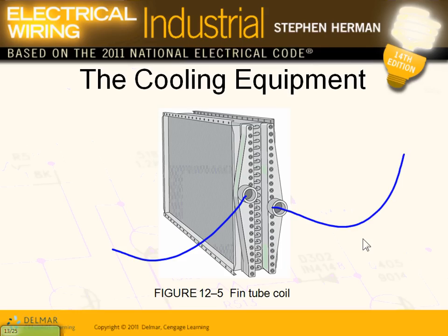This coil could be in the air handling unit, that would be an evaporator. Could be in the condenser, or it could be anywhere else. As a matter of fact, it's just bringing some type of hot or cold refrigerant into it, and you're blowing air right through it through a fan. You have to have a fan.